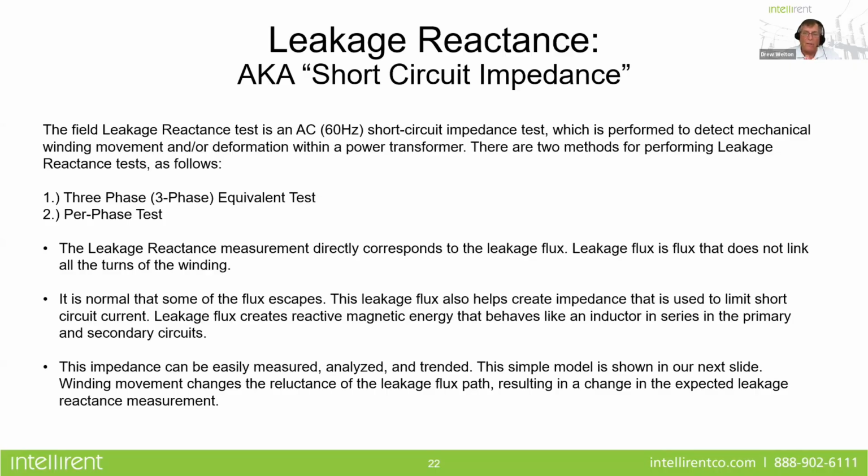Now, there is another test that is important as well, and this is called the leakage reactance. We used to call this, or still do sometimes refer to this as short circuit impedance. So think of this: you have a wooden trough running downhill, and there's water in that trough. Well, naturally, some of the water will spill out normally, and think of that as flux, some normal flux leaking out of the transformer. Well, let's say you come along and you put a big rock in the middle of the trough. You're going to get a lot more water spilling over, and it's the same principle with leakage flux.